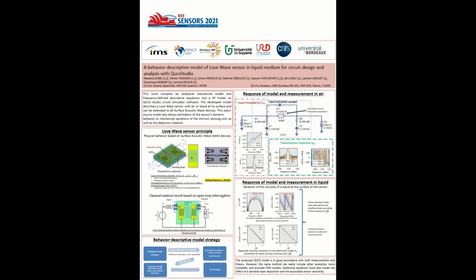Our modeling strategy is quite simple. First, a set of analytical models help us to estimate some characteristic constants of a Love wave device, following some geometrical or material choices, such as the IDT wavelength. These models help us to estimate the Love wave celerity and the mechanical sensitivity in liquid medium.